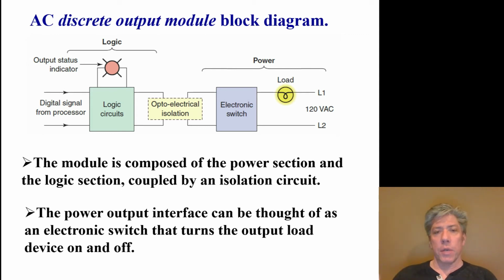And hopefully this will help you understand why you really need some source of power for output modules, because really all you've got, in this case, if it's like it was before, is a transistor that's making connection. That's all it really is. There's light shining on the base of a transistor. That does not generate power to make a lamp come on or turn a motor. All that does is apply contact closure, or connection, if you will.